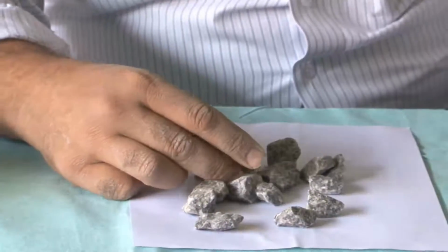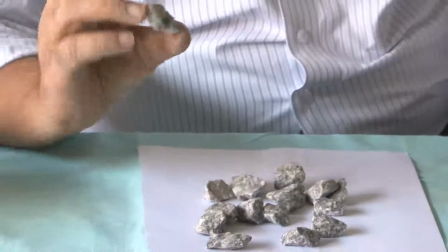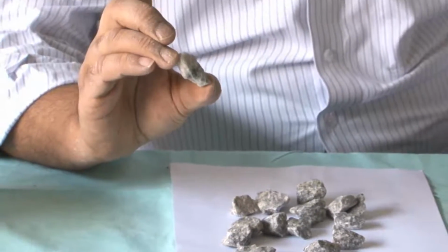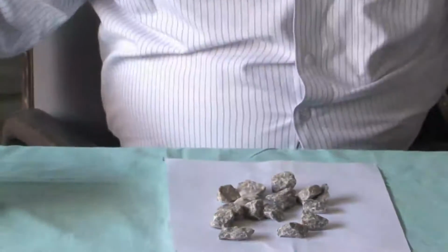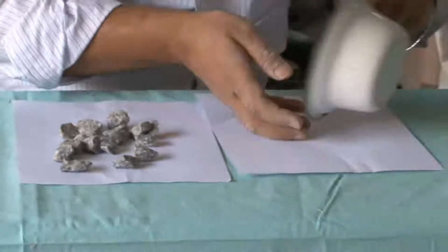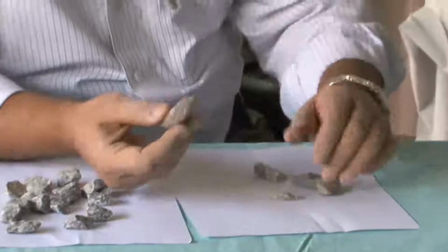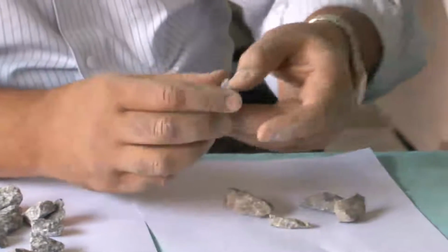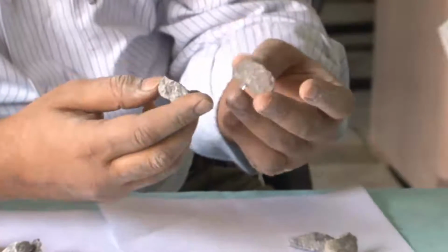We have to be careful that we do not have too many particles which are like this, which have one dimension which is longer than the other 2, and that part is controlled by determining what is called the elongation index. So, here we see some of these particles which are elongated, that is, one dimension is larger than